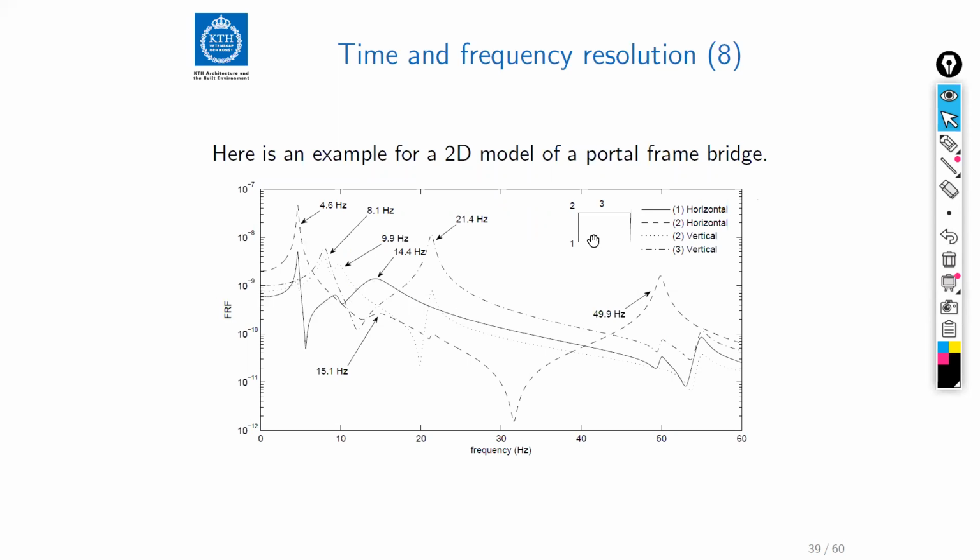And so it should be mentioned here that this portal frame bridge is coupled with the model of the foundations that includes the wave propagation and the dynamics that go on in the substructure, in the foundation. So there are no boundary conditions on this node. So we can put a force there and we can get a response. And in this case, it would look something like this.